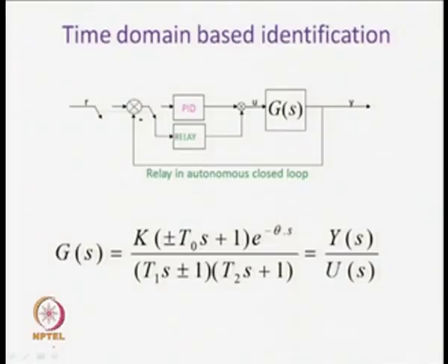These things we have already seen in our last lecture, where we considered an autonomous closed loop relay control system. The PID controller has been detached and an asymmetrical relay has been connected to the system to induce sustained oscillatory output. The form of output, depending on the type of input to the system, will have some specified form, and the input from the asymmetrical relay, which has heights h 1 and minus h 2, will be of the form shown here.